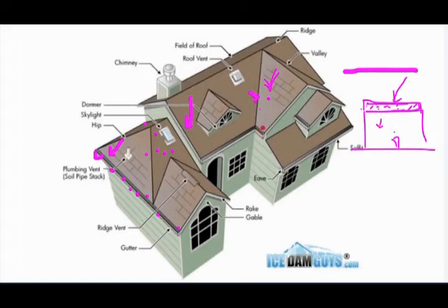And the other problem, which Beyza mentioned, is that while the snow is coming and suddenly falls down from here, this part is all broken, taking the heat with the ice and the snow. All of them will put pressure on this gutter and take it down. That's why it easily breaks. That's why the flat roof is the best one in climates which have less snow and rain.